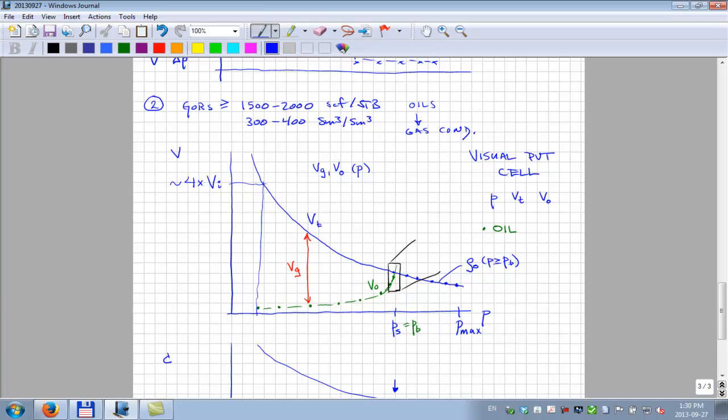Okay, that there's a calibration error in the liquid volume. In other words, if they could see just the liquid volume filling everything, they wouldn't get the correct total volume. So you can have this. The oil volume is an independent measurement, and it needs to really be calibrated accurately to make sure that it's giving you the correct physical number of cc's of oil in the cell.